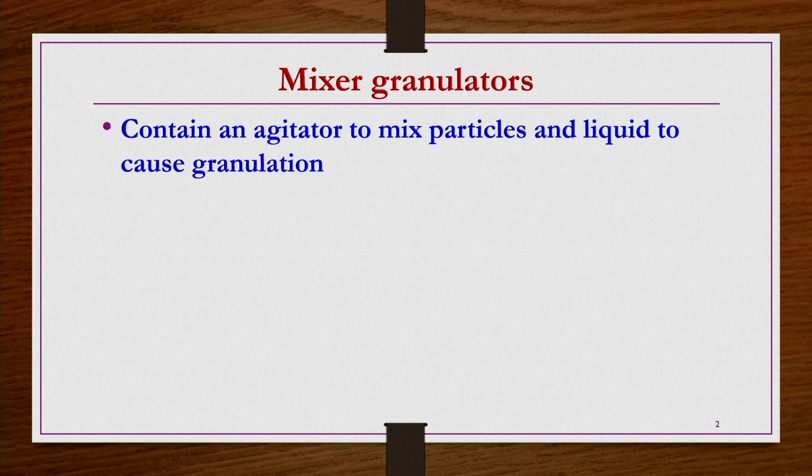In general they contain an agitator to mix particles and liquid to cause granulation. Whatever the binding liquid is, that and the particles are taken in a kind of mixer and then agitation is caused so that the mixing of the particles and the binding liquid will take place. Because of that, a kind of granulation will take place.